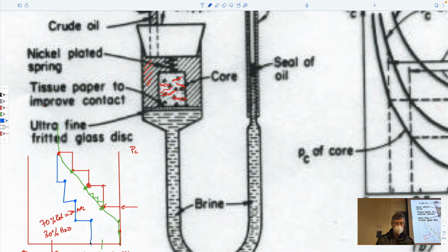And you decrease again. And pressure goes to this point. So the only ones we're interested in are this one, this one, this one, and this one, because they represent the equilibrium pressures. Once it's reached equilibrium, the fluid will creep in on this curve, the so-called drying curve. Drying curve because you're drying water out of here. The water will then creep back in once you go down this curve, the so-called imbibition curve.